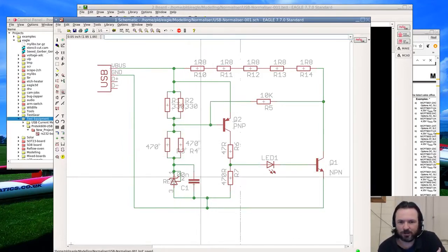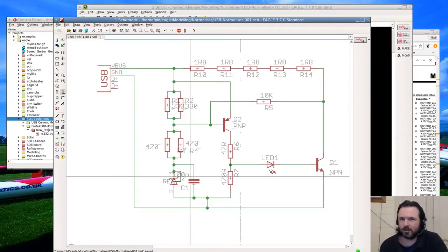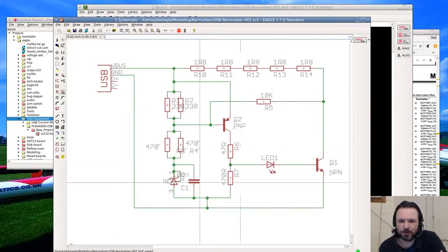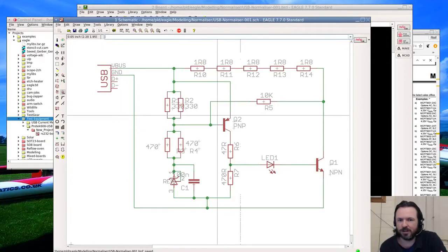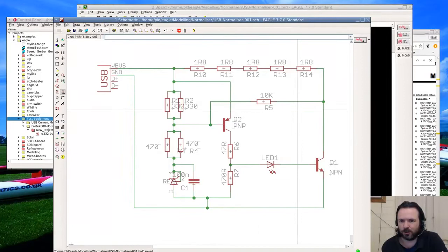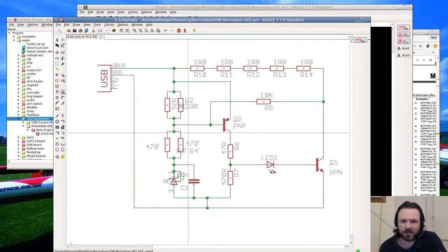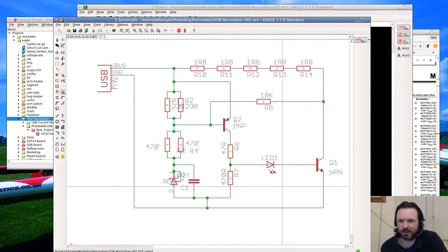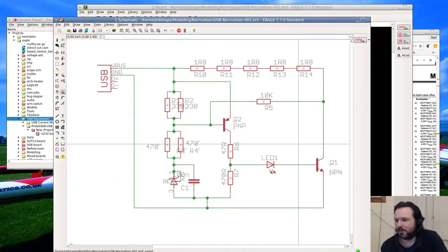Now the reason why we have a little capacitor here is sometimes if it's marginal with the startup, we're sort of cheating. It's a bit of a bootstrap that will temporarily, for a very short time, short all this to ground, so we'll get an absolutely definite enough of a voltage here between the rails and the base to get this conducting. So it's kind of like a forced attempted start, and if the voltage of the battery is low enough, it won't succeed, and it will just pop back up anyway. So that's basically how it works. It's a little bit of a convoluted contraption, but it works well. It's cheap and it's easy.